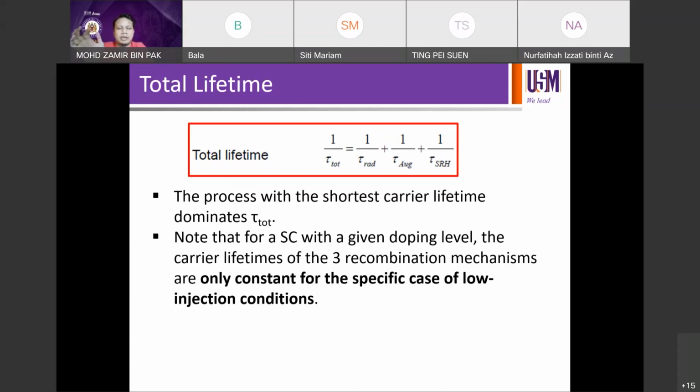So generally you want the lifetime of your carriers to be as long as possible, especially when you have to extract the carriers out of your semiconductor material or device. If the lifetime is short, it means before you can extract the carriers to outside of the device in order to complete the circuit, for example, they are already gone. They didn't have time to get out because of the short lifetime. This short or long lifetime tells you about the quality of the material you are working on, the electronic quality to be exact, right?